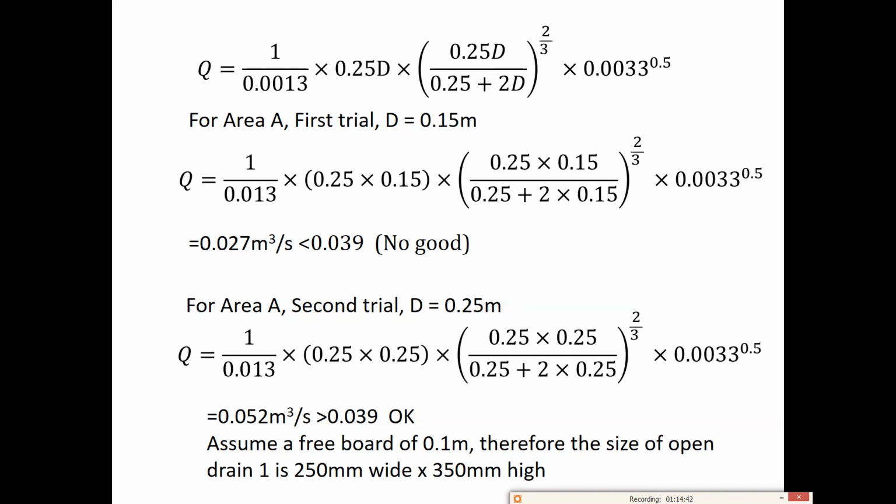If it is smaller, then the stormwater pipes or the open channel will be undersized, under-designed, and the capacity will be smaller. If you design a covered or bridge area and it is under-designed, the whole thing can be damaged, destroyed, even washed away. So we use a trial and error method, making sure that QM, the Manning discharge, is bigger than QP, the peak discharge.